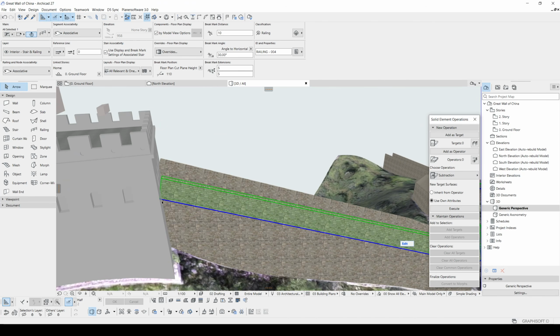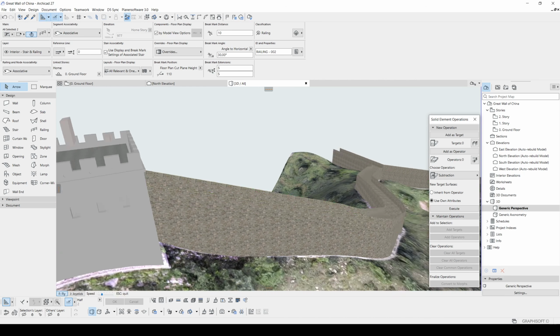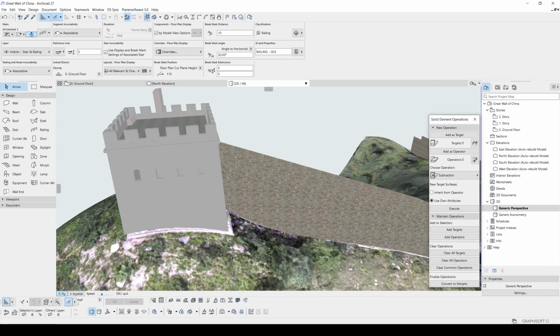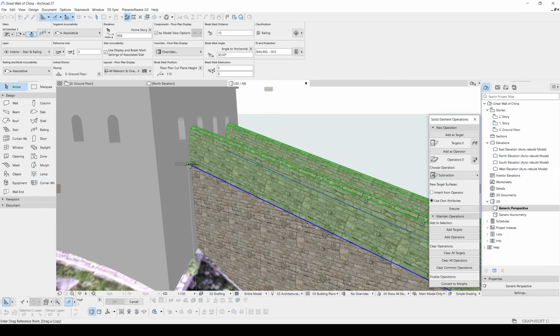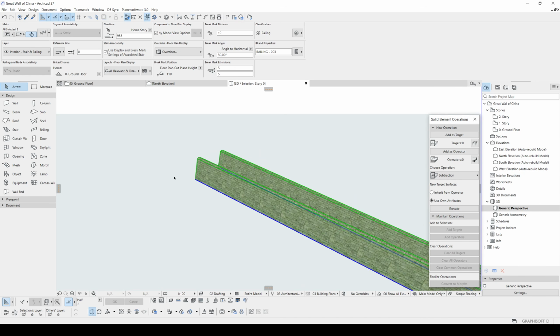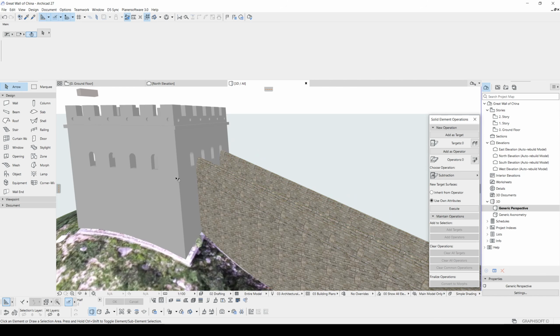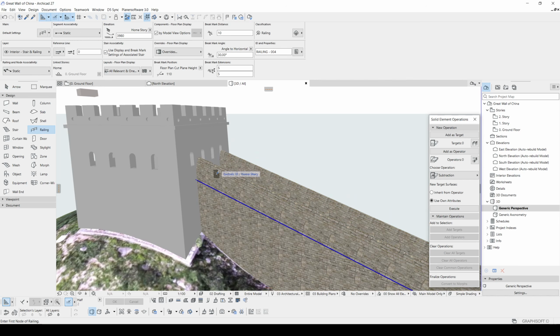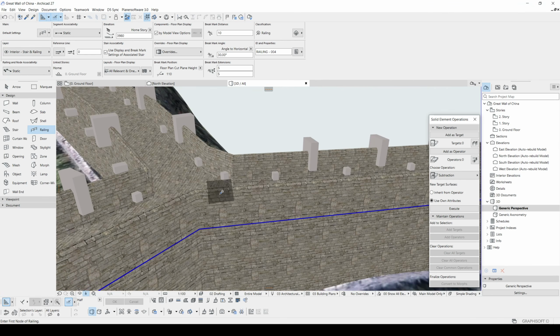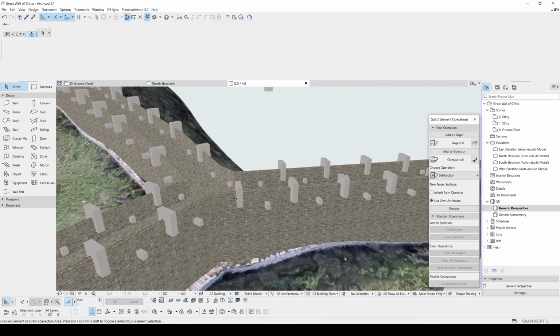Now, once we achieve this, we are going to duplicate these rails. Let's select them with the Shift. Let's just hit Ctrl Shift D from keyboard and click the same corner again. And now this is duplicated. We are going to copy the settings from this opening rail to this with Ctrl and Alt. Let's do this for all rails, just like this.